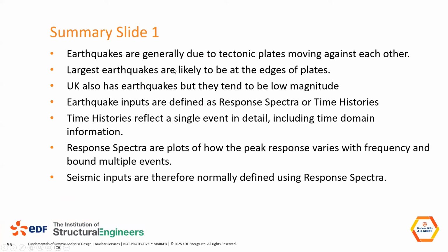Earthquakes, it's the same points as before. Due to tectonic plates moving, the largest earthquakes are at the edges. We have some in the UK. We define them in terms of input as a response spectra or a time history. A time history is one event. It includes time domain information. A response spectra is peaks only, and it includes an infinite number of events that match that peak. We generally use response spectra as our input, and if we need time histories, we derive them from the response spectra, or we develop sets of them to match.